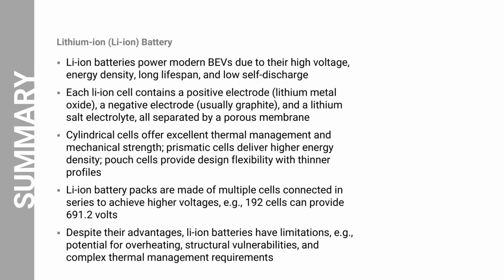Cylindrical cells offer excellent thermal management and mechanical strength. Prismatic cells deliver higher energy density. Pouch cells provide design flexibility with thinner profiles. Lithium-ion battery packs are made of multiple cells connected in series to achieve higher voltages. For example, 192 cells can provide 691.2 volts.